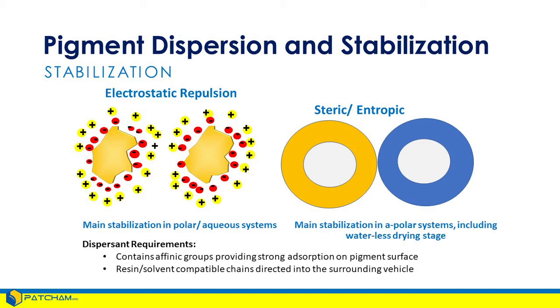And then they prevent the pigment particles from making physical contact. Be aware that if you modify the solubility of that liquid medium system, so you lose the solubility of that dispersant, that polymer chain will coil up because now it's not happy in the continuous medium. And that reduces the physical spacing between these pigment particles.